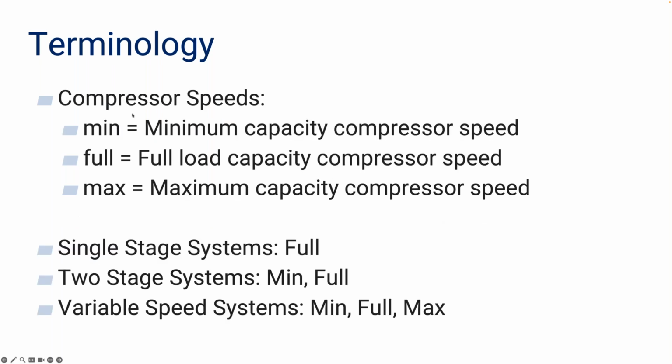The other piece of terminology is compressor speeds. So we use minimum, full, and maximum. What most people think of, and what most of the ratings, the AHRI ratings, are provided at, is full capacity. Single stage systems only have one speed, so that's what we call full. Two stage systems use minimum and full, and for variable speed systems, we use minimum, full, and maximum.